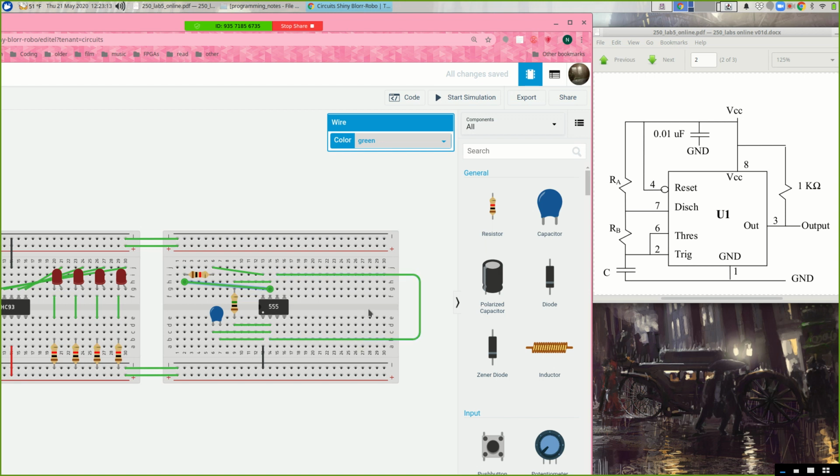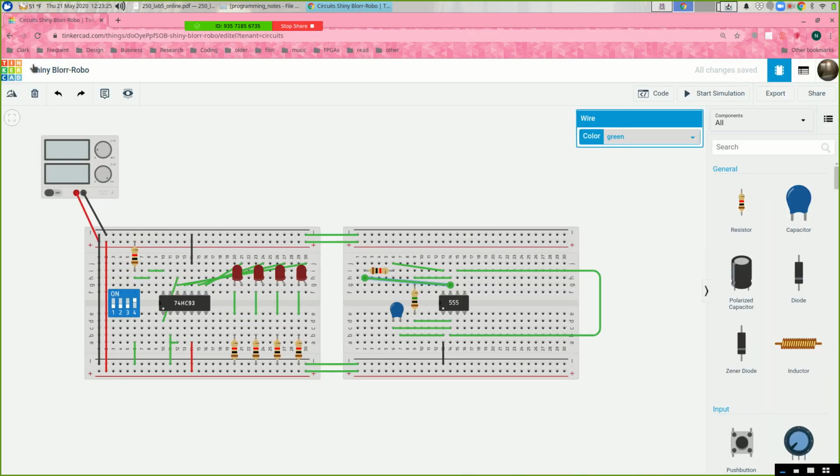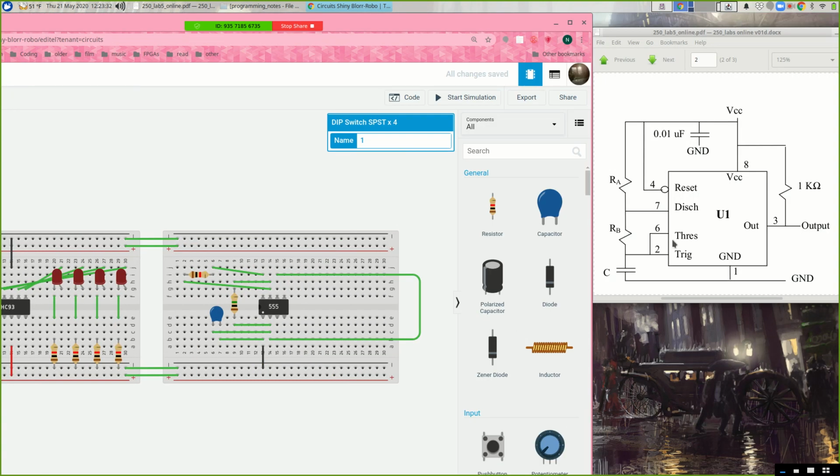Yeah, rotating is kind of cool. It doesn't work well for switches. They don't actually rotate the way you'd think. But for resistors, it's handy, and probably for LEDs too. So yeah, for rotating, I just use this symbol up here. Once you select a part, that'll rotate it. Alright, so we've got the resistor from 7 to 8. That's also supposed to be 1 mega ohm.